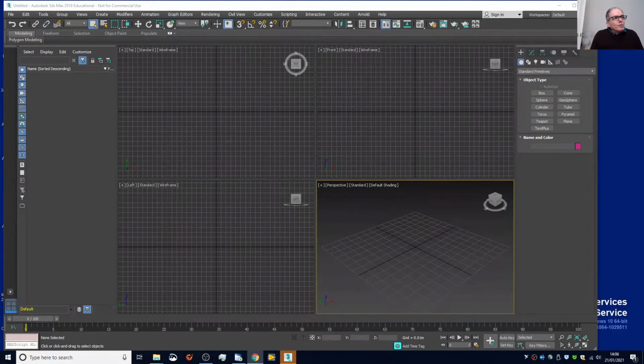What you also need to know, so we're talking here a little bit of background in terms of theory, and then we're going to start working in more detail. What's important to realize is that from an animation point of view, don't use groups, use links. Okay, so you do linking and put the parents and children, and don't do grouping. That's not a good idea to do an animation.